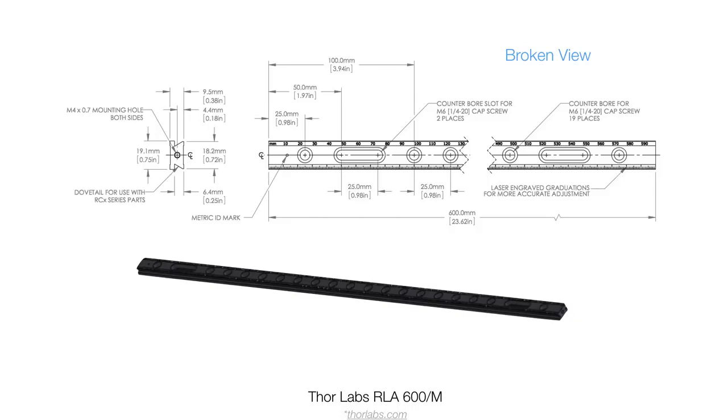If you have a part with a very large or small aspect ratio that would be tough to fit on the page and keep at a reasonable size to show detail, you can use something called a broken view. To make a broken view, you can take your part, add some jagged lines in there, and break out material to keep the size how you'd like it.